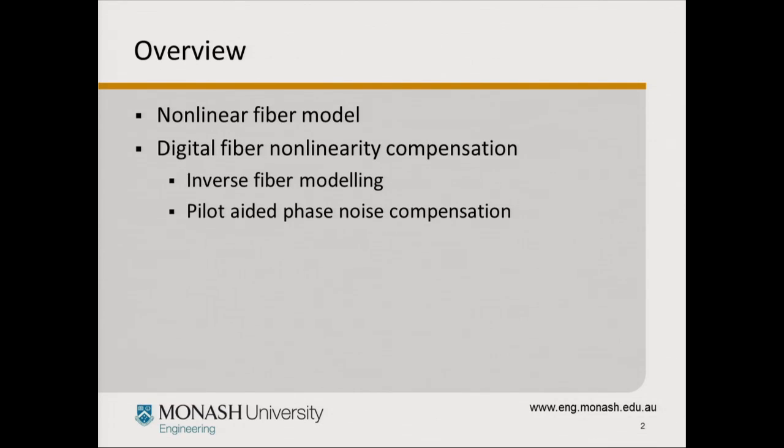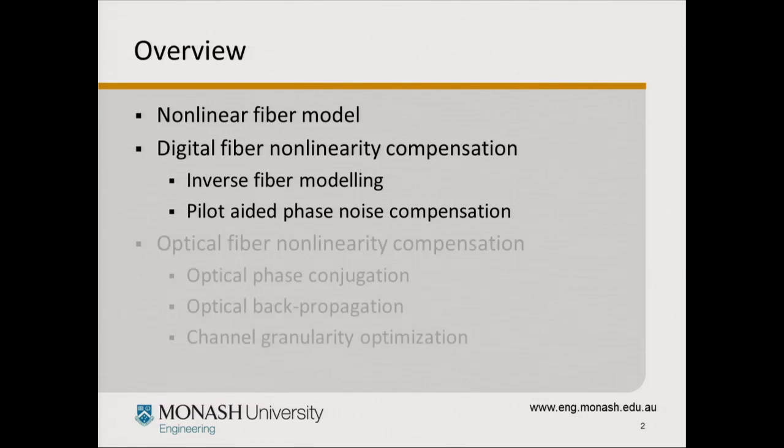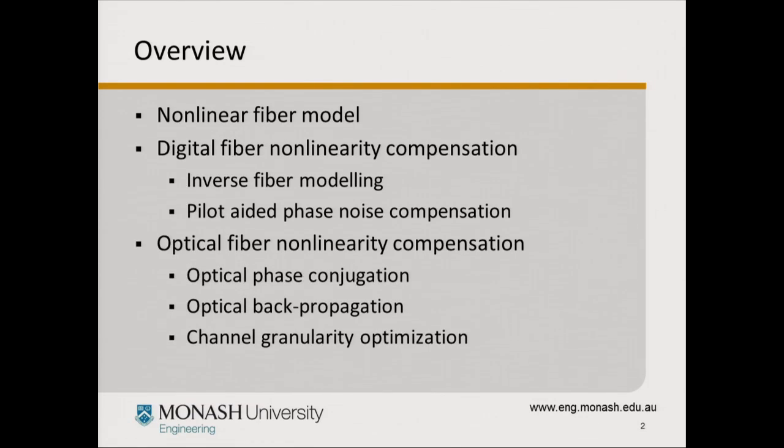These are techniques that you would use with DSP either before the electrical to optical conversion at the transmitter or after the optical to electrical conversion stage at the receiver. And then at the end I'll present some optical nonlinearity compensation techniques. These are techniques that are done entirely in the optical domain without using electronics or digital processing.